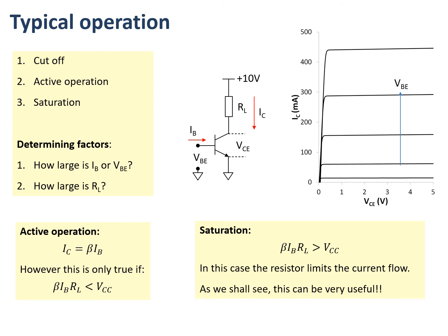And it's the same in the saturation situation as well. In the saturation part, the current is rising very rapidly as it goes from 0 up to the active region, and that's influenced by the voltages that I apply, but it is also limited by the RL value. That resistor will limit the current that can flow through the device. So as I impose different values of RL, I will see the current flow being affected, not just by the voltages but also by that resistor value.